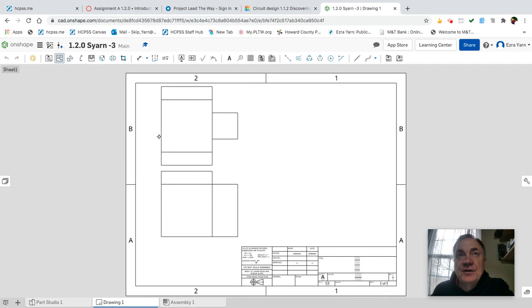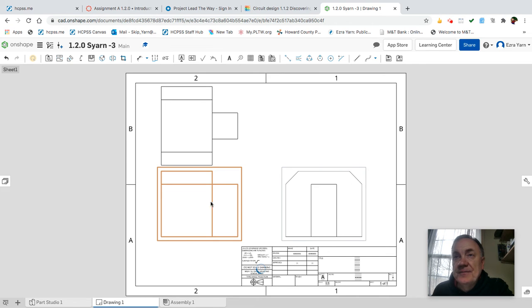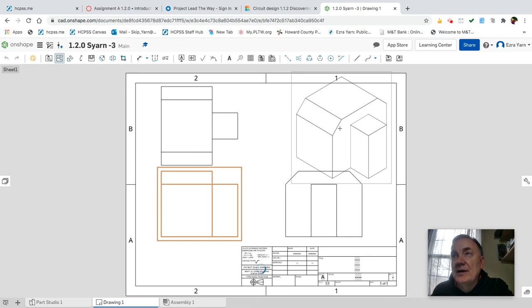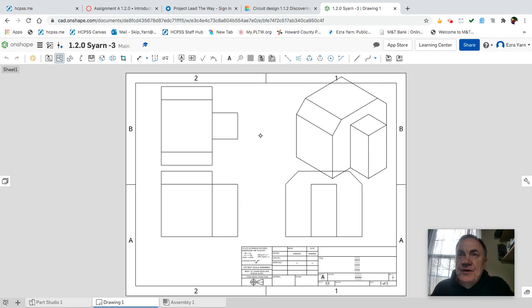I'm still in projected view. Notice that's blue. So I will click here and say let's project that over here. And I'll click here again and project it up here in the corner. Now notice these items are all coming in really big. After projecting all four of those items, I'm going to hit Escape and then come back to the front view, which is the bottom left.